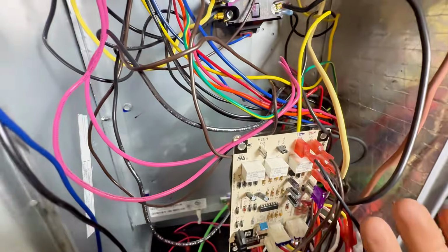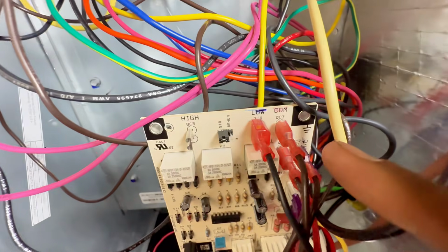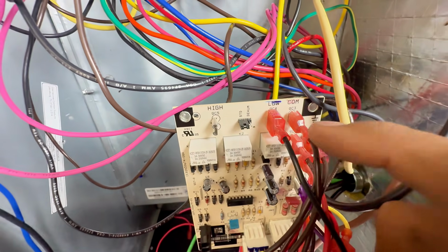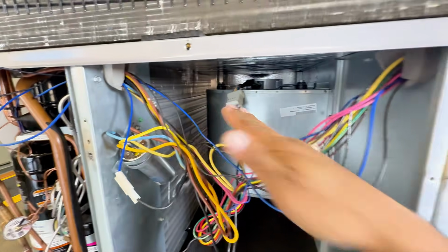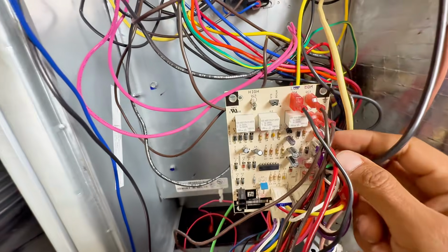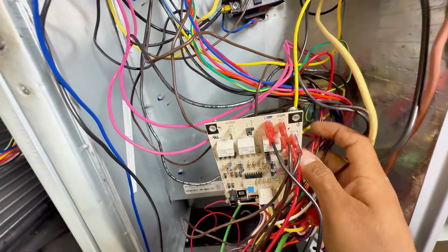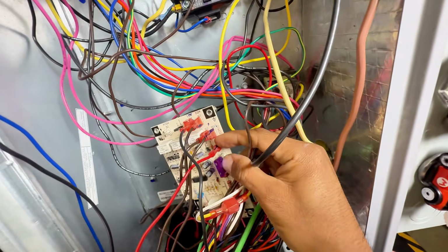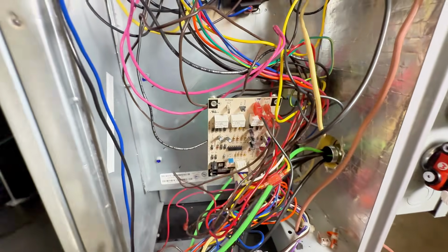Okay, so I was able to pull the boards out. It's still a little bit messy, don't get me wrong, but just to kind of briefly go over it, that common and that low, which is 24 volts, is going to my ECM motor on the low voltage side. And then you see right here, this red wire and that brown one, that's coming from my transformer. That is where the transformer supplies the board with 24 volts. And that's my fuse right there, okay? And then my defrost board is on the bottom right here. But let's go ahead and talk about Luigi's path.